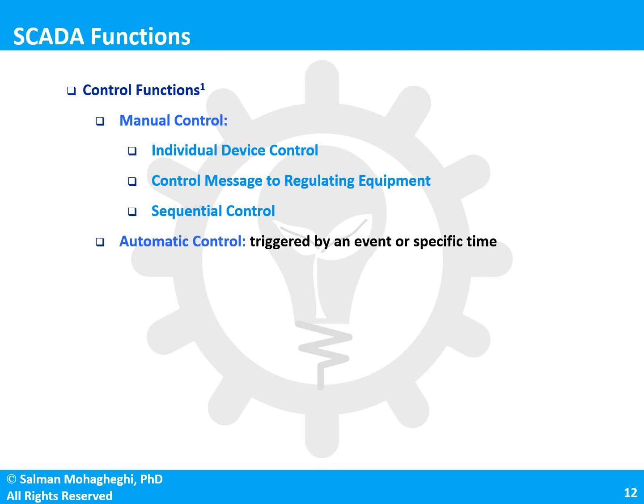Control functionality is also another important aspect of the SCADA system, again being part of its name, supervisory control and data acquisition. This could be manually implemented by the human operator, or it could be automatic. A human operator can implement a manual individual device control.